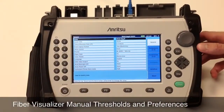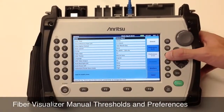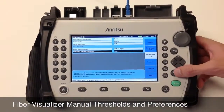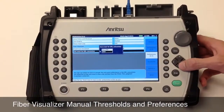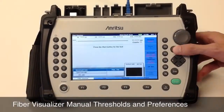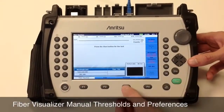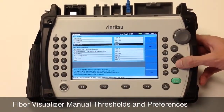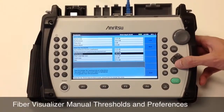Before beginning the test, make sure that your preferences and thresholds are set correctly. There are two preferences that are specific to the Fiber Visualizer software found in your Preferences 2-2. You can adjust your auto detect and pass-fail thresholds in this screen.